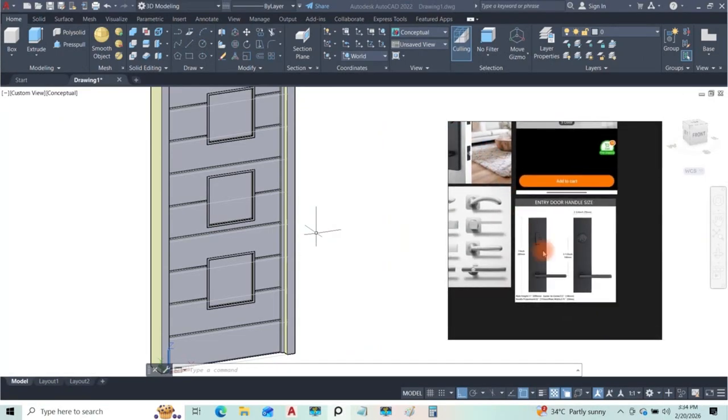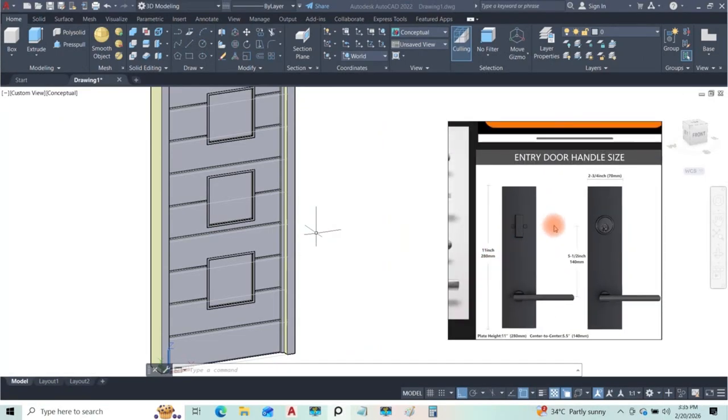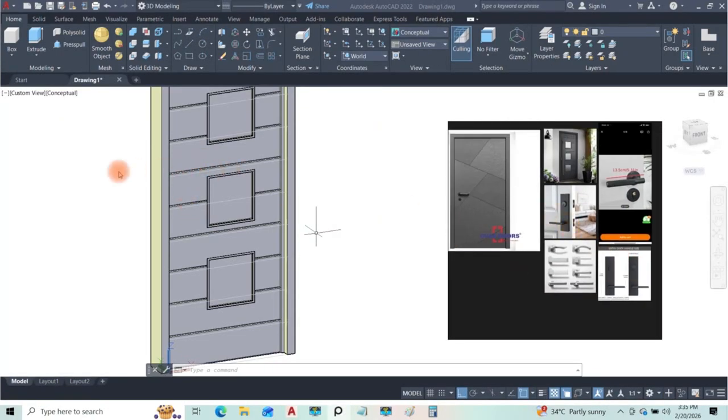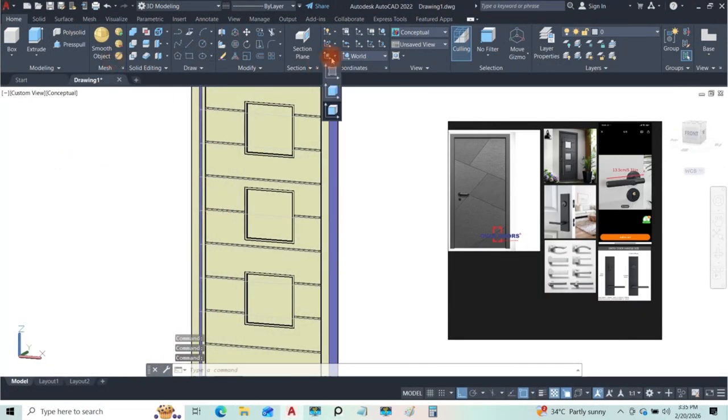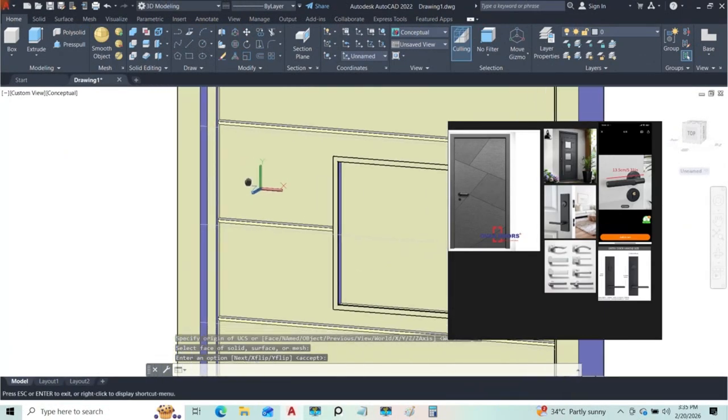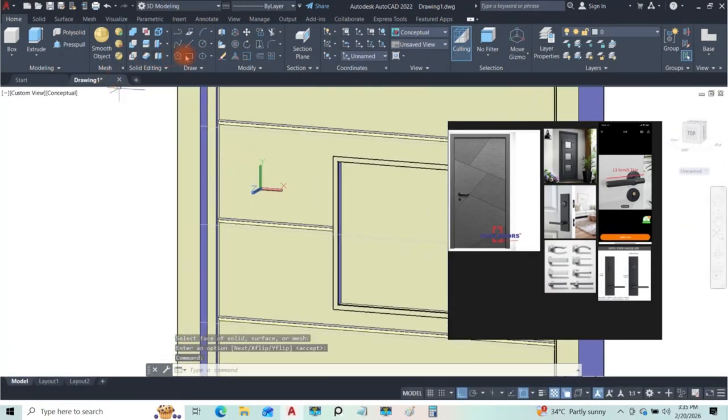So let's start by creating this first, before we can now start looking at this surface. So don't forget, we have 280 by 70. So let's select a face. We are going to pick this face as our working plane, press enter, and then we can now start rectangle, and just pick here. We have 280 by 70, right?